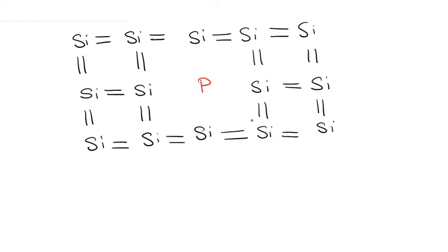Okay, but it is sitting in the silicon crystal structure. The mother material is silicon, and it is, let us say, doped with 0.25% or 0.5% phosphorus. So it is surrounded by silicon atoms.